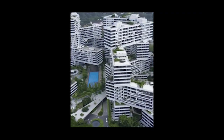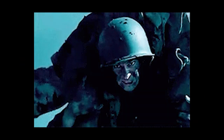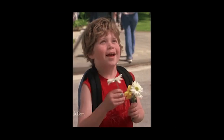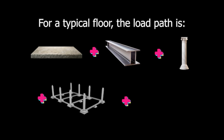Now, let's talk about load transfer per floor level. In a multi-story building, every floor has its own load. People walking, tables, chairs, partitions, cabinets, appliances, and floor finishes all create load. The first structural member that receives this load is the floor slab. The floor slab is a flat horizontal surface that people walk on. However, the slab does not carry everything by itself. It transfers the load to the beams, then the beams support the slab and transfer the load to the columns. Then the columns carry the load downward from floor to floor. For a typical floor, the load path is floor slab, then beam, load transfer to columns, downward to the foundation, and then to the soil.